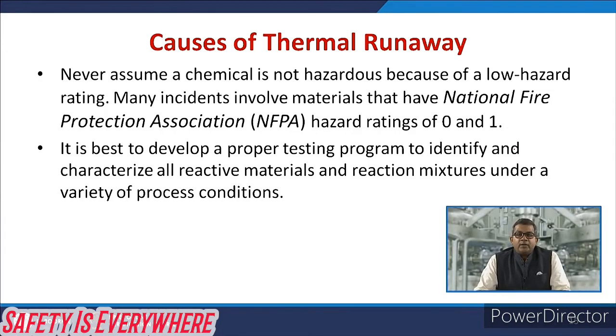So never assume a chemical is non-hazardous because of a low hazard rating. Many incidents involve material having a National Fire Protection Association hazard rating between 0 and 1, but they became catastrophic in due course of time. So it is best to develop a proper testing program to identify and characterize all reactive materials and reaction mixtures under a variety of process conditions.